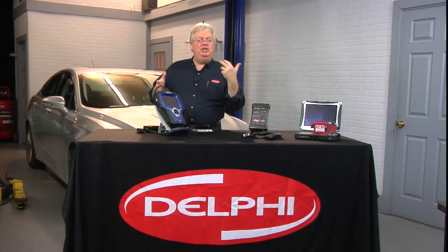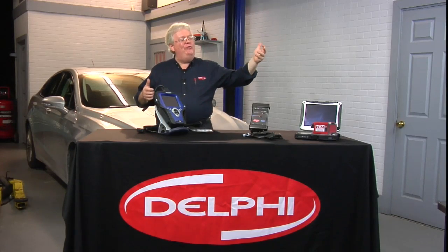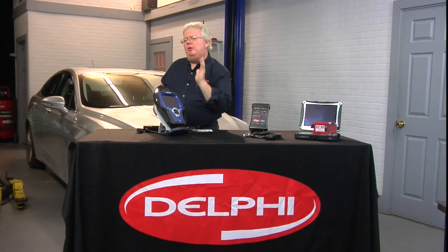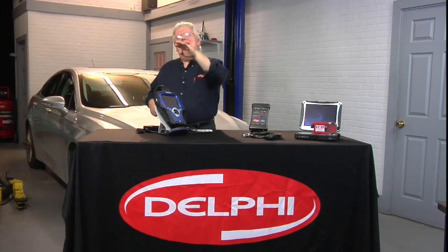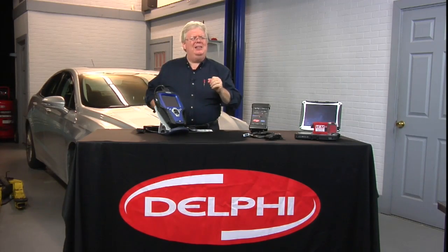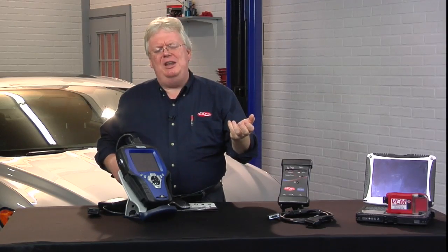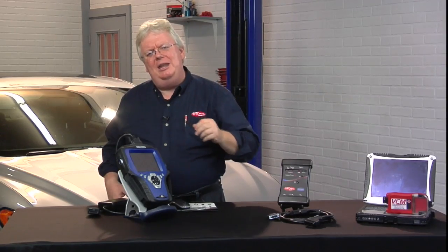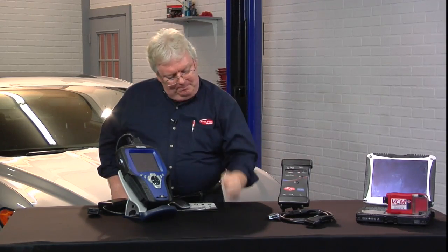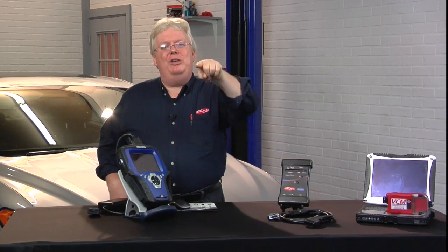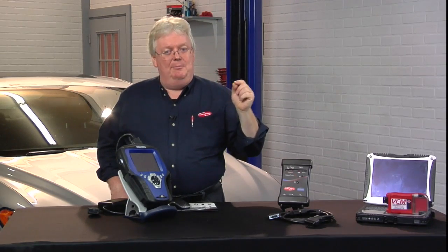So the frustration you run into: you had a code for an O2 sensor, or maybe a drivability problem with no code, but you found the O2 was just not too savvy. It was just a little lazy. You pulled it out, looks like it'd been in a chimney for a couple of years. You put a new one in, and you drive the car, monitors look complete, you didn't go to mode 6, there were no codes, no pending codes, boom, you put a stamp on it, call the customer to come and get it, and they come back in 2 weeks.